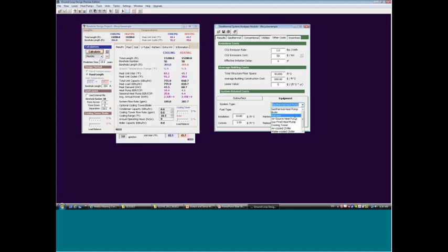Now I can go to my conventional system I'm comparing against. We had air-cooled chiller electric. I have an installation cost here. Let's say it's about $6 per square foot. Predicted controls costs, maintenance costs, replacement time frame. Natural gas boiler was the other option. You can see my different variables I input here. Again, it comes with a pre-populated database with some general guidelines, but everything's customizable.